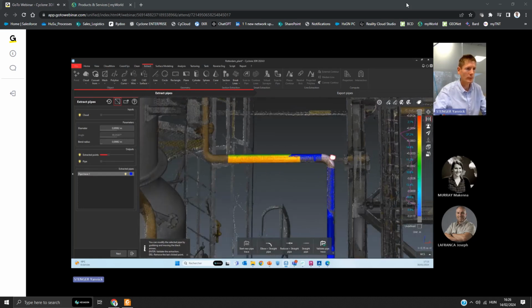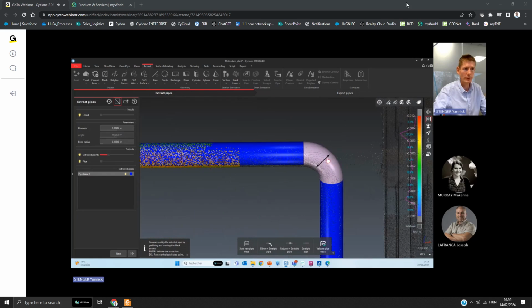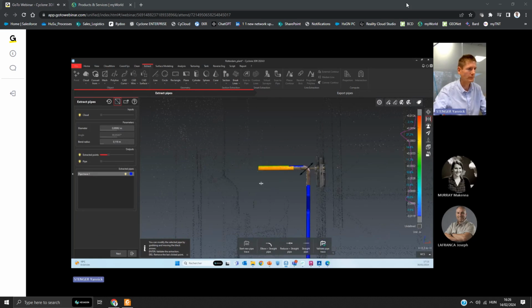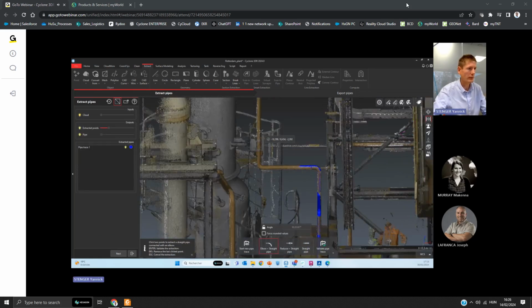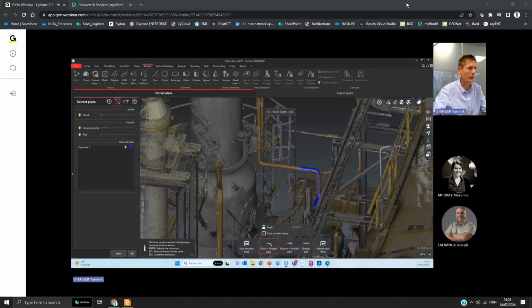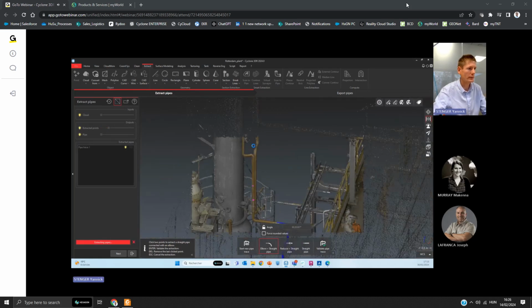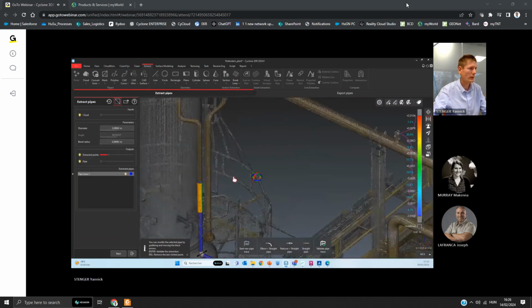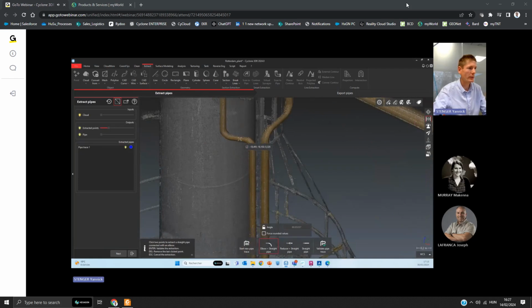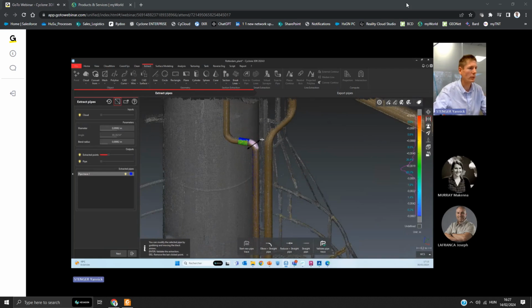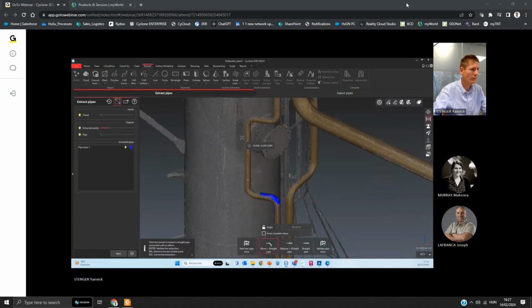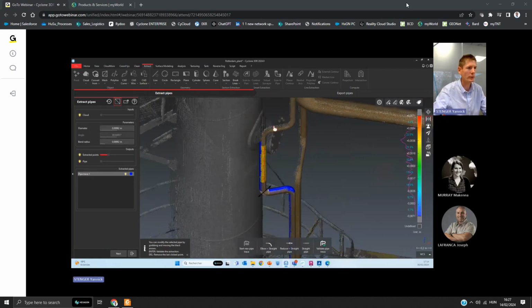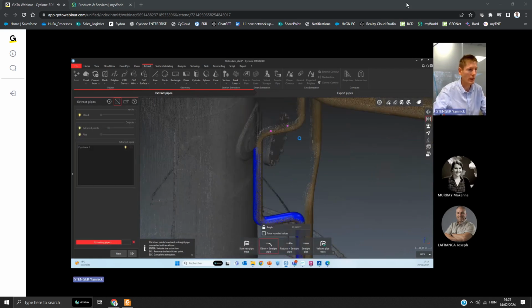Please note that we automatically connected the capacity to edit an elbow and its bend radius, and I can click enter and then move forward to the next step of my extraction. Please note that the diameter is saved from one straight part to the next one until I create a reducer, which is also supported in this first version of Cyclone 3DR.